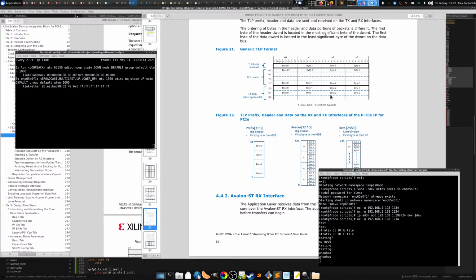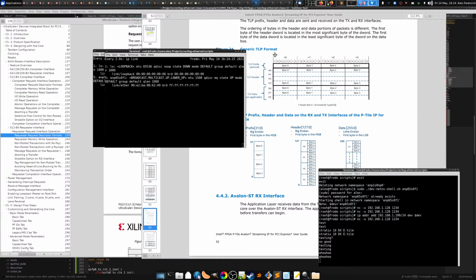And it's also ended up tripping me up a couple of times. With a design I was working on a while ago, I was having issues with timing closure on one particular output register that was, I think, driving the input of a DDR flip-flop or something like that. In the initial run, I didn't have a placement constraint or a timing constraint for that, and it ended up placing it in a really stupid location. Then I was trying to get it to resynthesize the design and move the register, but it just wasn't cooperating. It's like, oh, I've already synthesized this, I've already placed it, I don't need to touch it. So I ended up having to delete the entire project. Fortunately, I had my makefile set up, so I deleted the entire project and regenerated it, and then it worked. I'm like, what the heck? I couldn't even find a way to clear out the cache or something and force it to rebuild the project from scratch. So probably a button that I missed somewhere, but the incremental compile is not perfect, shall we say.